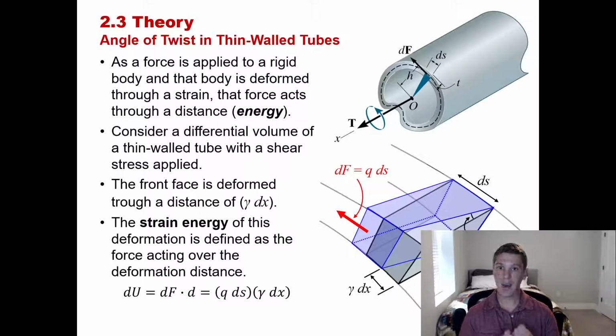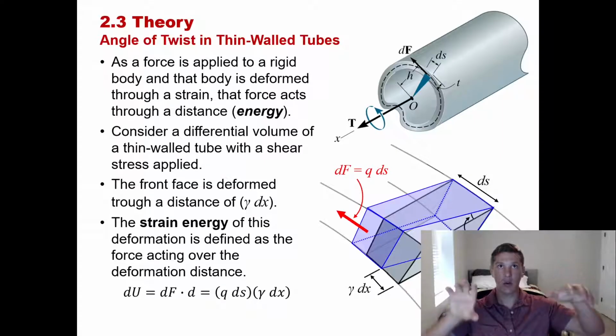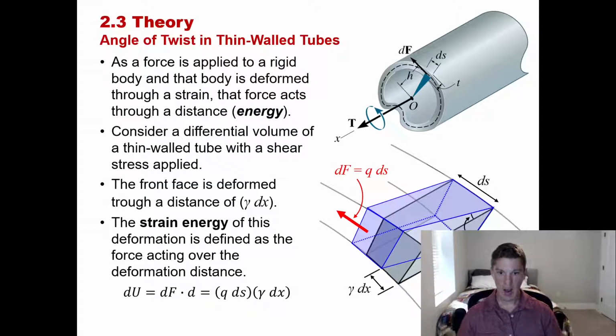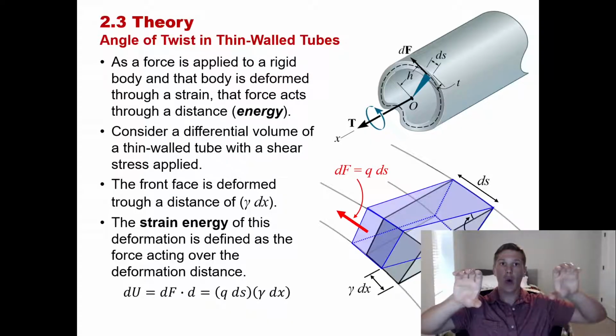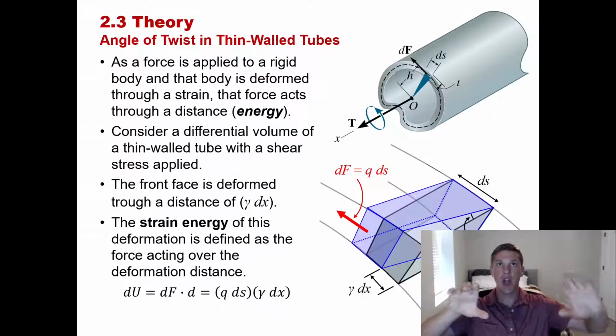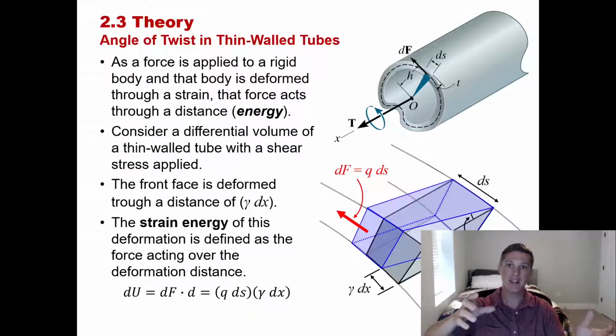The second thing that may be important depending on our application is that we can have a maximum angle of twist. If I have a shaft and I'm going to apply a torque on it, I may have a shaft that won't fail under a given torque, but under that given torque, there's going to be a relative angle of twist through that shaft that's so great that it's going to mess up the geometry of our system. So I may have to design my shaft that's holding an external torque.